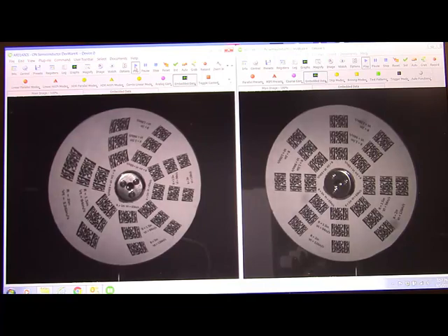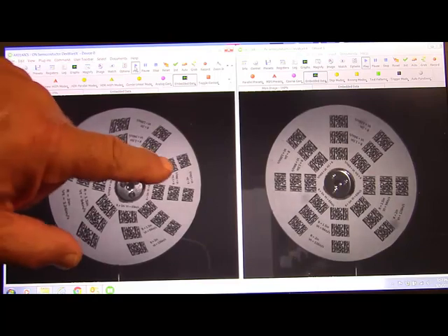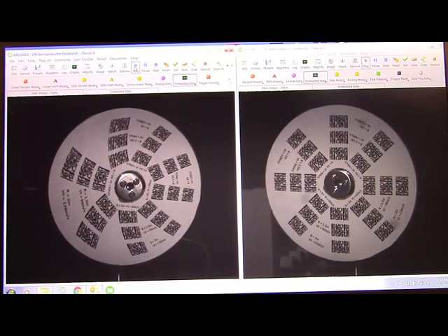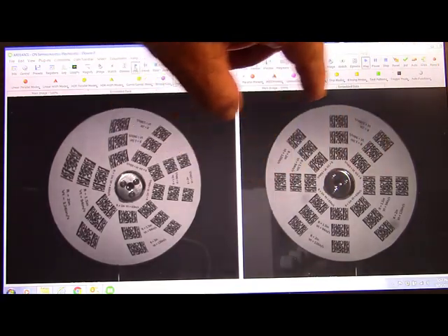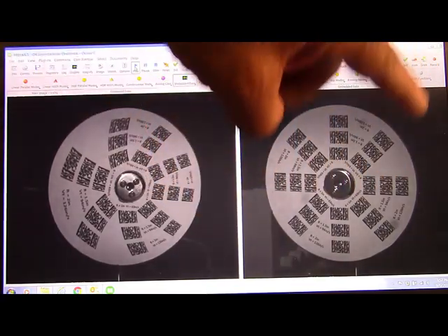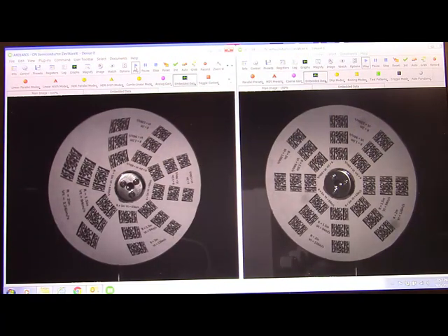While both sensors have the ability to acquire an image based on triggered timing, the rolling shutter sensor has distorted the barcode significantly. On the left it's stretched and on the right it's compressed, making the ability to read the barcode next to impossible. This rolling shutter artifact is caused because each row starts and ends its exposure at a different time. On the right hand, the AR0144 maintains the barcode shape and size in the entire image. This is due to the fact that each pixel has a storage location that allows all pixels in the scene to expose at the same time and be stored.